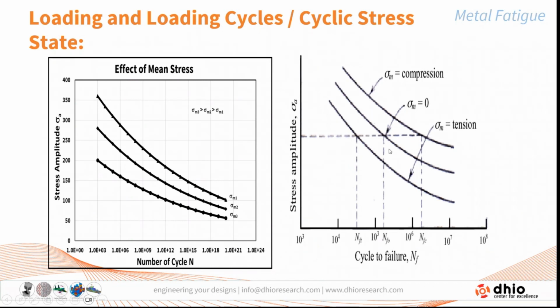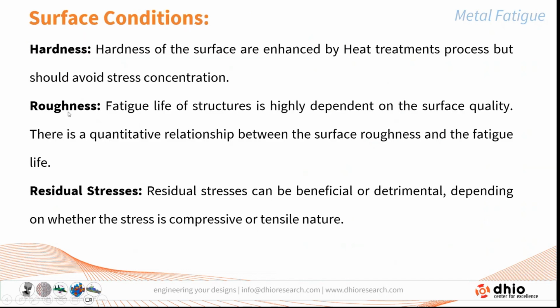So that's the reason one of the advantages is inducing a residual compressive stress in the member, as an advantage for the fatigue life of the component. And nowadays we see a lot of research going on for inducing compressive residual stress in the component so as to enhance its fatigue life. From this figure, one can see that when the mean stress is compressive, the fatigue life is increased.